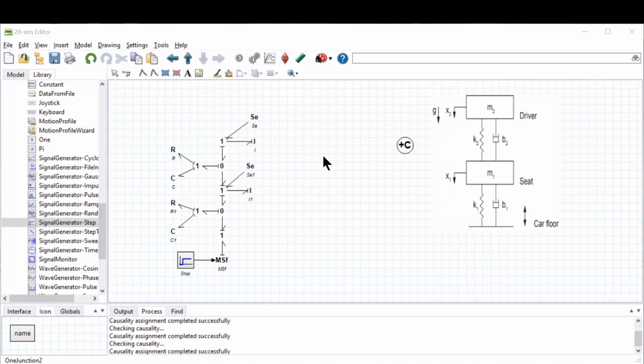Now, once you reach this point, you would like to see if your model is complete and there is no bug here. So this is the tool here. You double click here, and you see under the model some information that the model has 0 errors and 0 warnings. This is very good. I have 10 submodels, 17 equations, 13 variables, but actually 4 independent state variables.